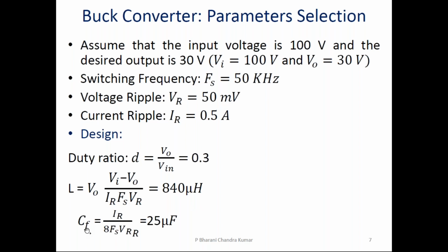I have represented it with CF just to avoid conflict with our state space matrices, x dot equals Ax plus Bu, y equals Cx. C has been used there, so I don't want to use C for the capacitance. That's why I represent it with CF, in the code as well. If you use C for both the output matrix and the capacitance, you will be in big trouble while coding.